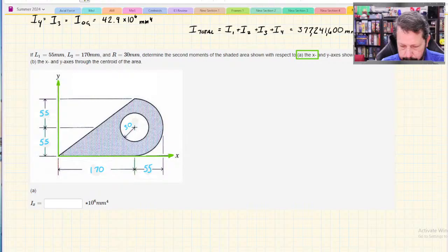You only have to do that when you are trying to do the flexural stress equation, but technically you can find the moment of inertia about whatever axis you want. And so, at least for exams and homework like this one, we might just give you an axis, so that you don't have to go find the centroid and then do the calculations. Here we're just saying use that x-axis that's given and find the moment of inertia for this wedge shape about that axis. So this works a little bit like centroids where I'm going to have two positive shapes.